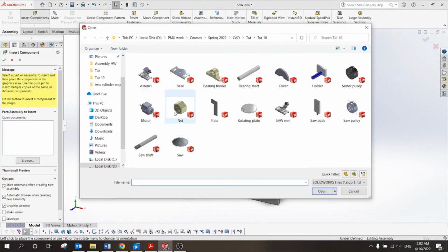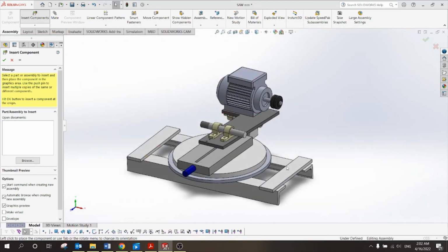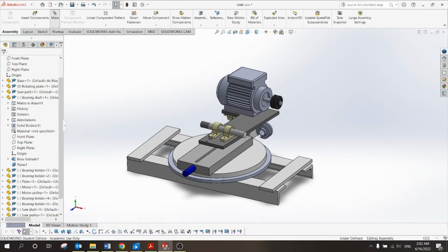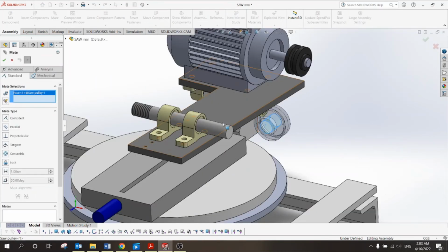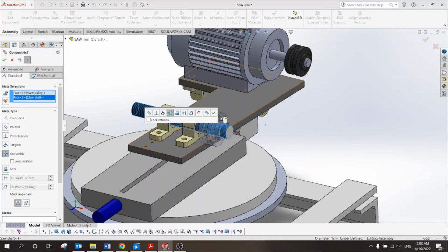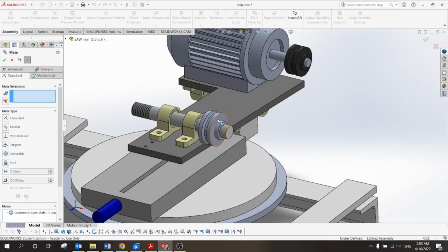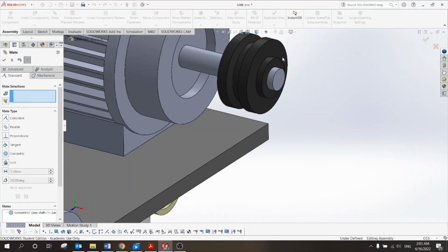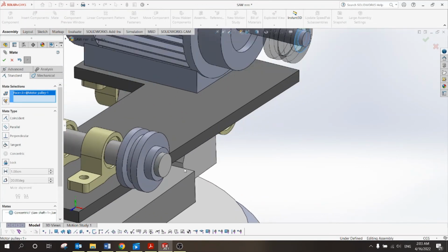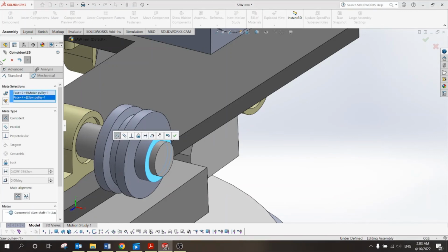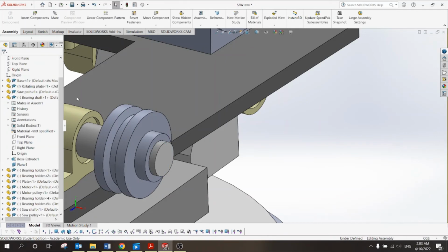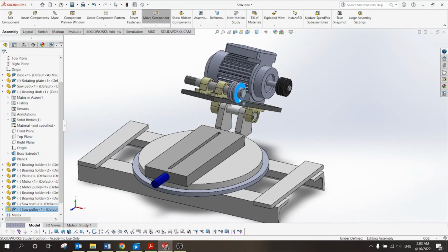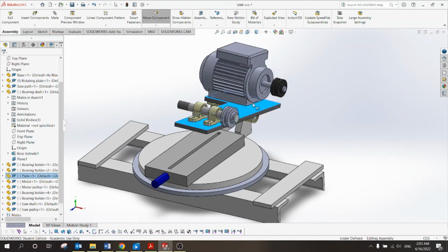Components, the saw pulley, and then I can bring it close to the shaft, mate cylinder with cylinder, and if you remember, I have to take it out to some specific distance, or simply I can say that this edge is mated with this edge, and that's it. So the two pulley systems are connected now, and the whole mechanism can rotate. Now let's go and bring the cover.